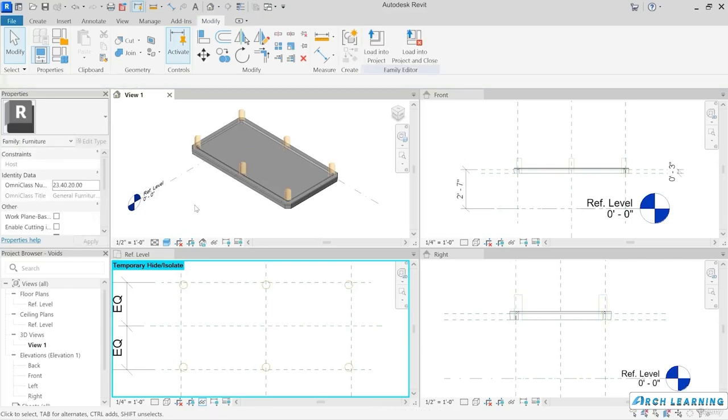Now, the reason I wanted to do it this way, other than that I like to do it that way to get the geometry correct first, is also I wanted to show you what a non-engaged void looks like. So notice that when you just have a freestanding void in your model, it will show up in this yellow transparent glass material. And that's how you can tell that that's a non-engaged void.